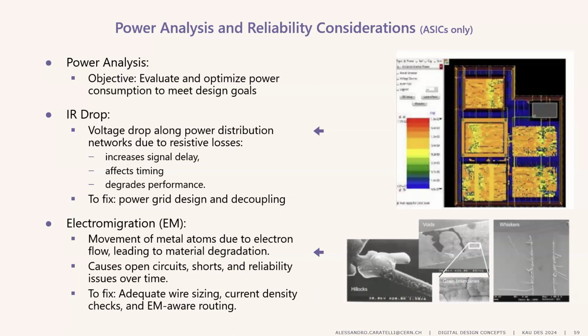Basically, for instance, for the IR drop analysis, you will initially need to extract the parasitics, so evaluate capacitance and resistance for each net in the design, and how much power each cell is drawing. The software will do this.